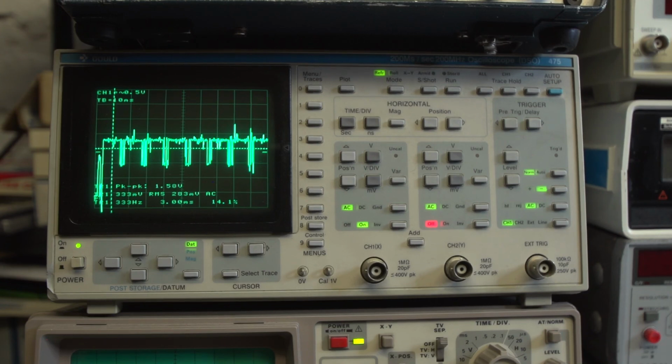Sometimes when you're doing fault finding, it's actually an advantage to use an analog scope. You don't always want a digital scope. Because everything's been digitally sampled through an ADC sampler inside the scope, you do get artifacts at certain frequencies. You've got to be aware of that when you're doing measurements and when you're testing things. It's not a case of what you see is what you get, not always. Whereas with an analog scope, there's no sampling going on, and what you see really is truly the voltage coming in. As long as you're within the bandwidth of the scope itself, it will look accurate.